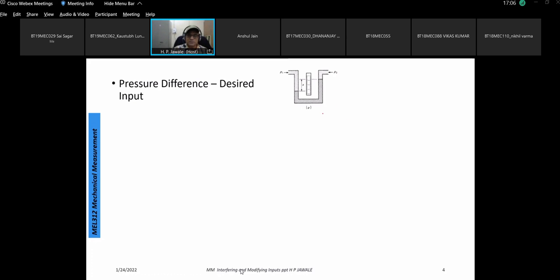Now in this condition, the pressure P1 and P2 ideally is going to create the difference of the pressure, say P1 minus P2, if we consider P1 is larger, which is proportional to the deflection on the scale or the scale graduations. We are going to make the marking such that it is going to be proportional. Say maybe unit pressure difference is equal to unit graduations made on the scale. So this is what is desired.